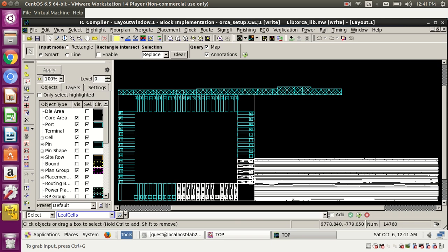It will check where the nets are crossing parallelly, and this is also M3 and this is also M3. Even M3 and M5 can also induce. Those are some other rules; it hardly matters. But it has to be there, it has to be an M3. It will check where the metal layers are parallel, with different metal shapes: one shape should belong to one net and the other shape belongs to another net. So these two nets are not the same.